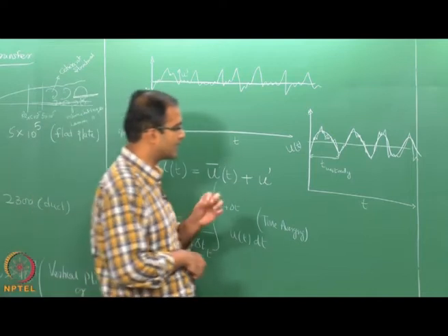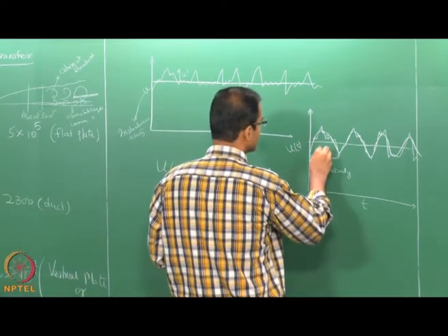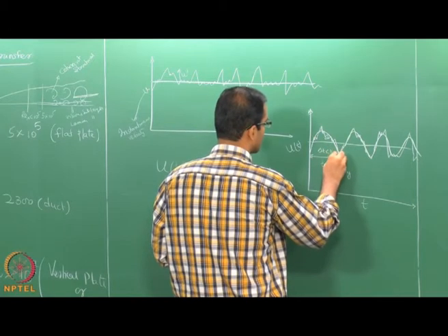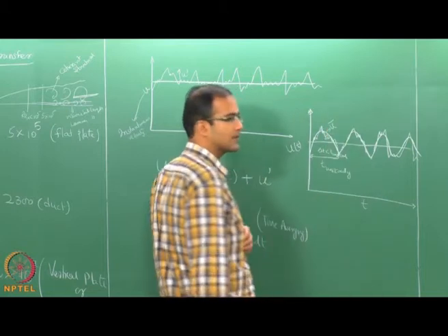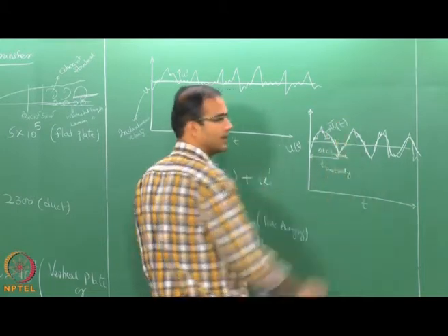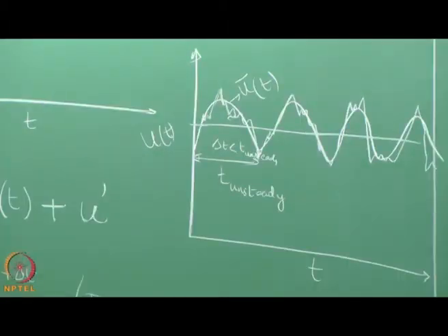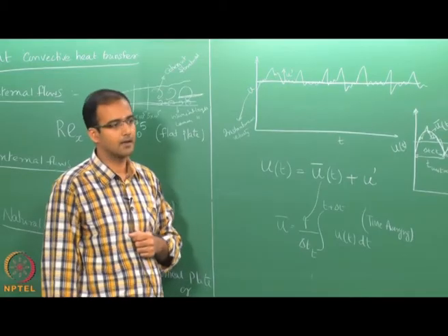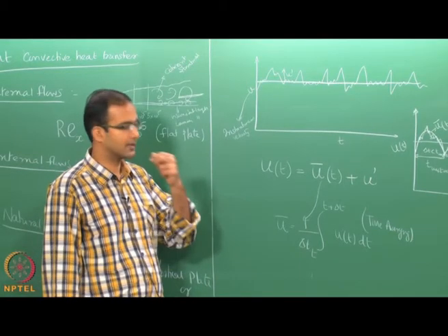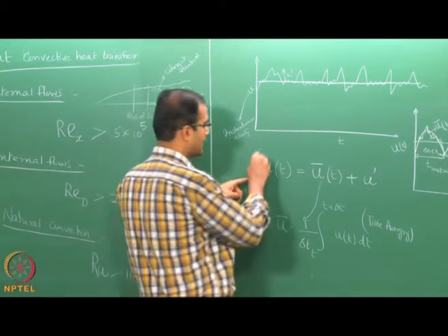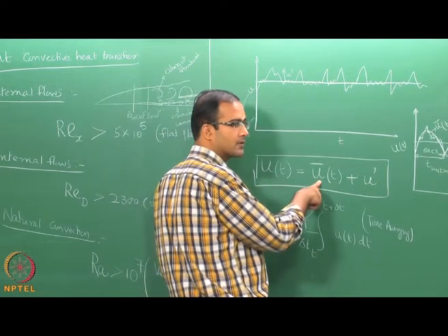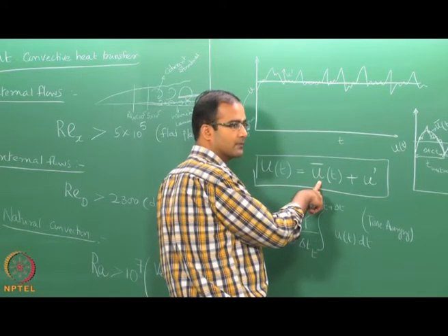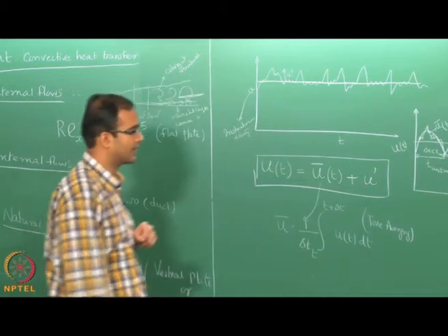So, if you select that delta t appropriately, then you should be able to reconstruct u mean, which is actually a function of time. This is showing that there is a periodic unsteadiness in the flow pattern, the mean flow itself, and this is coming after you apply the appropriate smoothing. And therefore, the correct representation will be to say that an instantaneous velocity can be decomposed into a mean, which is a function of time, plus the fluctuating component.